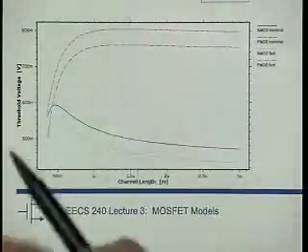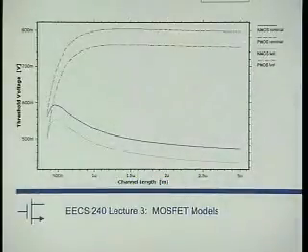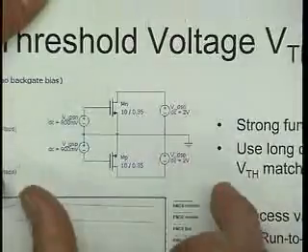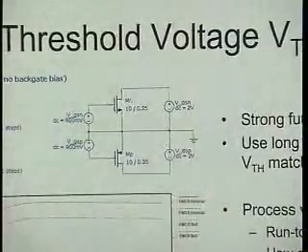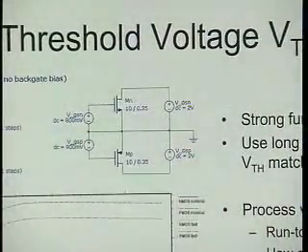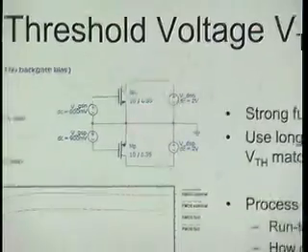But you have to look up in the HSPICE and Spectre and so on, all these different versions of SPICE, they use a slightly different way on how to do that. So you have to look it up in the manual. But then it's very handy. I also, in all these slides where I show how to extract threshold voltages from SPICE, show the circuit for how I do that. They're usually very simple, but sometimes require some thinking, like when we looked at capacitance, right?